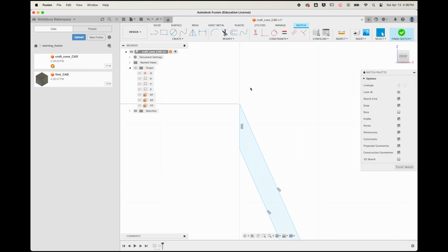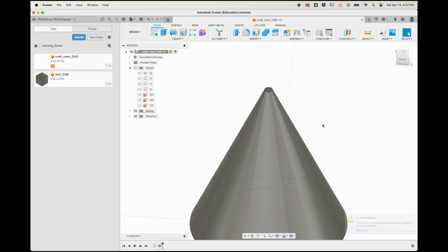Come back to your sketch and activate the line tool and draw a horizontal line that snips off the top of that sharp top. And by horizontal, I just mean you're looking for this little square corner icon, promising that you are 90 degrees to your vertical line. With your horizontal line in place, activate the trim tool and get rid of the remainder of that horizontal line and the remainder of your sharp top, these two little line segments up here. Good. We've now flattened off the top, better than pointy.